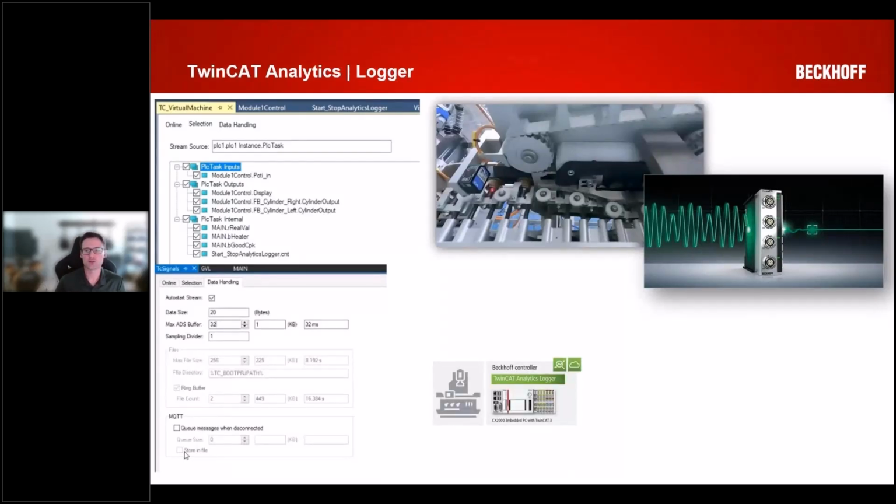All right, so for now, this logger works on the controller itself. You have two options. The data points you select are either pushed to a central broker, as we already illustrated in a distributed model, and that information will be sent as a continuous stream over MQTT. Or if this system exists standalone in isolation, you can also log directly to the controller's non-volatile memory.